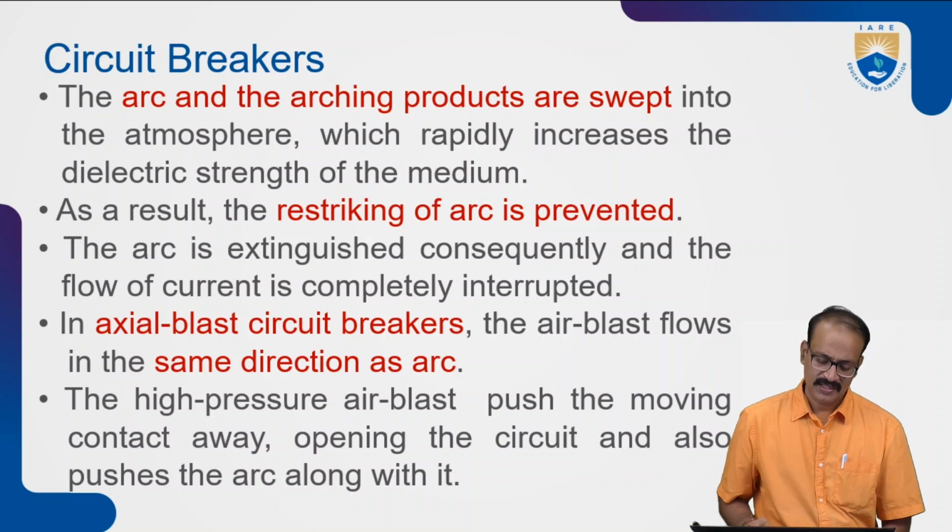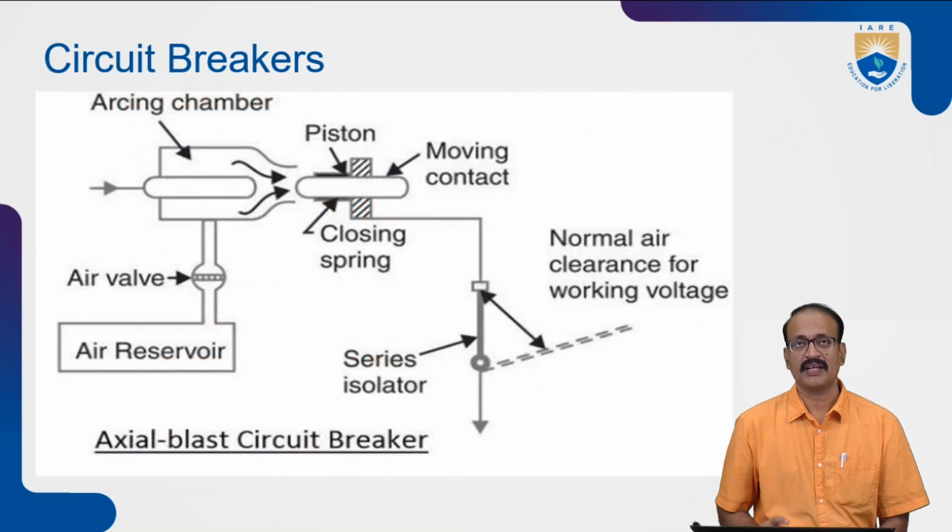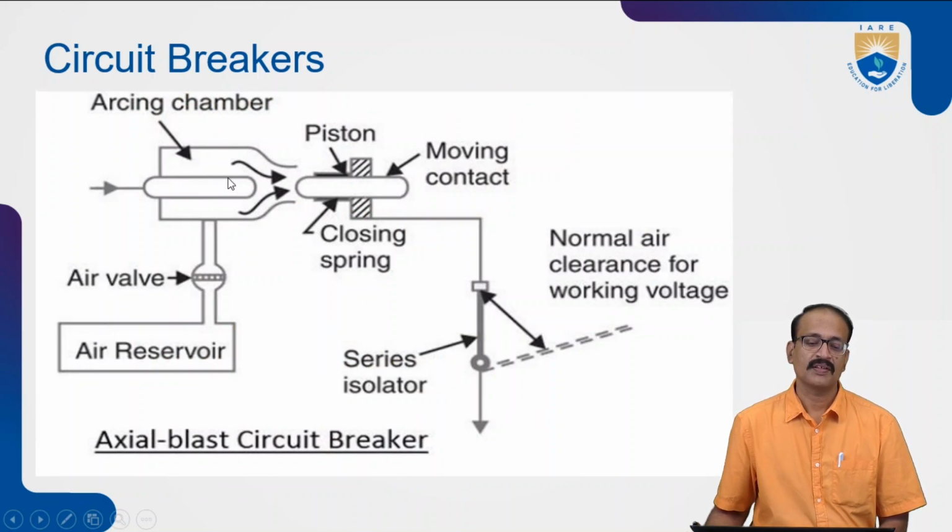It starts from the fixed point to the moving point, and in parallel it forces the moving contact away, blasting the arc and avoiding the restriking also.